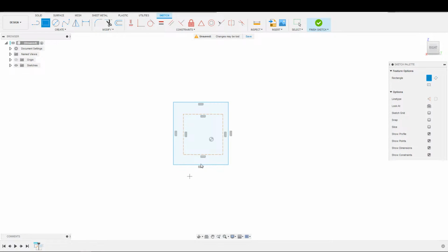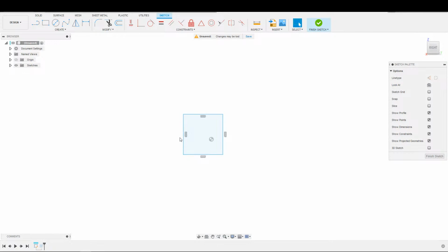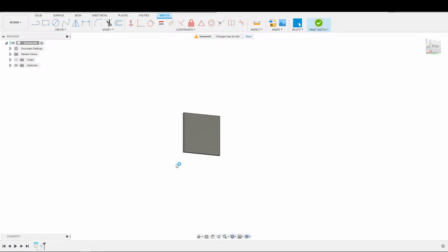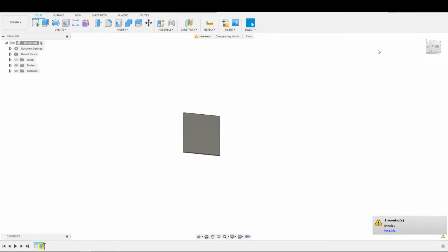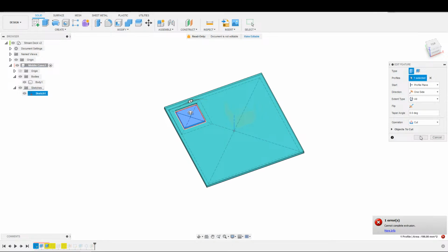I was hoping we'd be able to do the opposite. So basically start out with this, which you see still works. It still works because it knows it's there, even though I deleted the outside one. That internal profile is still selected when I do the 2 selections for the extrusion, and that's why it still works. I was hoping, however, that it would look at this internal profile and go, okay, that internal profile bled out to the outside. It just extended outwards, but obviously that did not work, as you can see there. So that was my rationale for trying that. Did not work. So we're just going to have to come back in here and fix these guys.